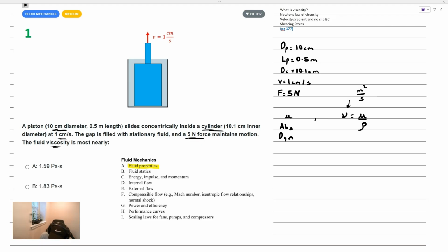The dynamic viscosity has a force inside of its unit. The standard unit for the dynamic viscosity is a pressure times time, right? Like a Pascal second. And you can see that inside of the choices here, we have Pascal seconds as one of the units. A Pascal is just a Newton per meter squared times a second. It's a Newton second per meter squared. You can see that Newton, a force, is mentioned inside of the set of units if we look a little bit more closely. So we're really talking about the dynamic viscosity as this force inside of those units.